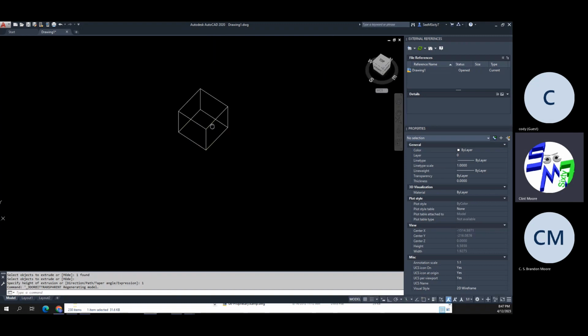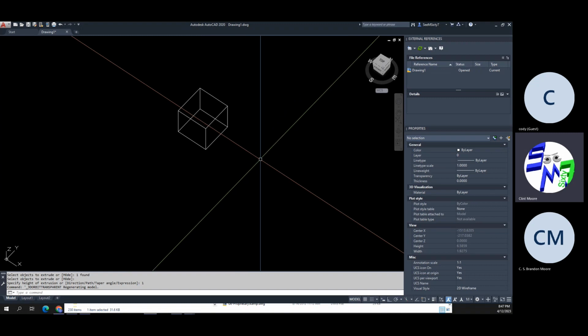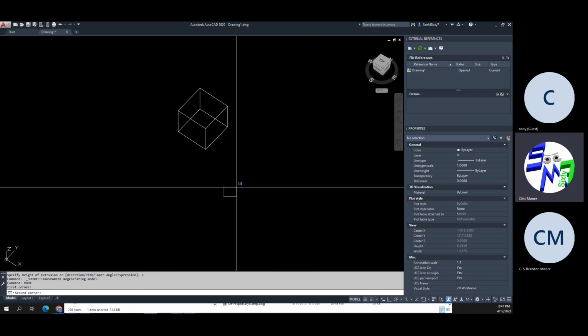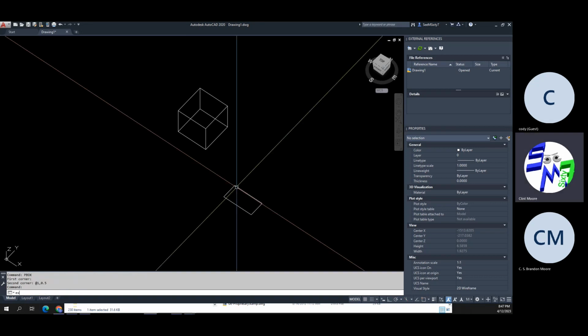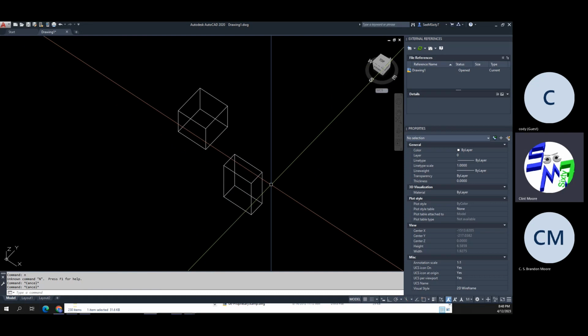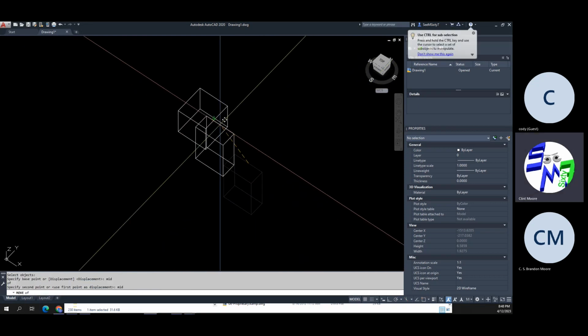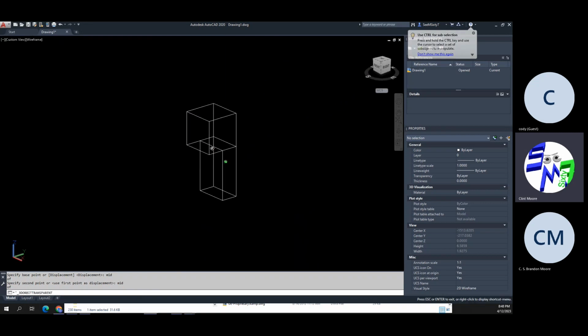All right, now we're going to draw his body. I'm going to say that's a half by 1.5 PBOX. I'm going to say this is at 1, 0.5. Extrude this 1.5. And I'm going to move that up underneath him from mid of that to mid of that. Okay, so now we have his upper body.